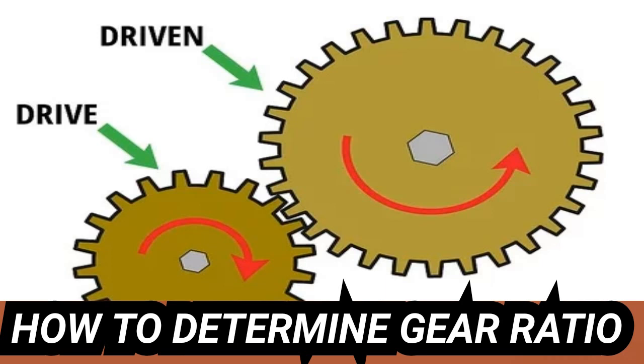Question: if the wheels are spinning at 500 RPM, what would be the gear ratio? Community answer: in order to answer this question, we need to know the drive shaft RPM. Once you know that, it's very simple math to determine the ratio. Question: how is the velocity of the gear ratio dependent on the radius of the gears? Community answer: for two gears to be driving, meshing against one another, they must have the same tooth design, pitch. So a gear with 80 teeth compared to a compatible gear with 100 teeth should have 80% of the diameter.